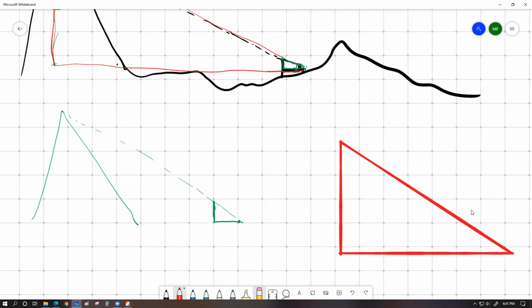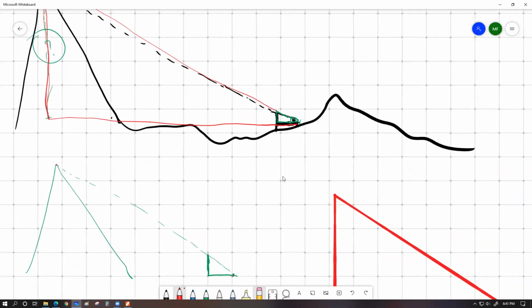This is also an indirect measurement. We did not actually measure the pressure under the true atmosphere. We actually measured the pressure under a mercury column. This is an indirect measurement. Understood? So when we measured height with the barometer, we measured the height of the mercury column, calculated the pressure from it, and that pressure is the atmospheric pressure. In this case both of them are equal. And for the previous case we are actually measuring this one, and by using the same angle we calculated how much this one is. So there is a ratio between them in terms of trigonometric similar triangles.